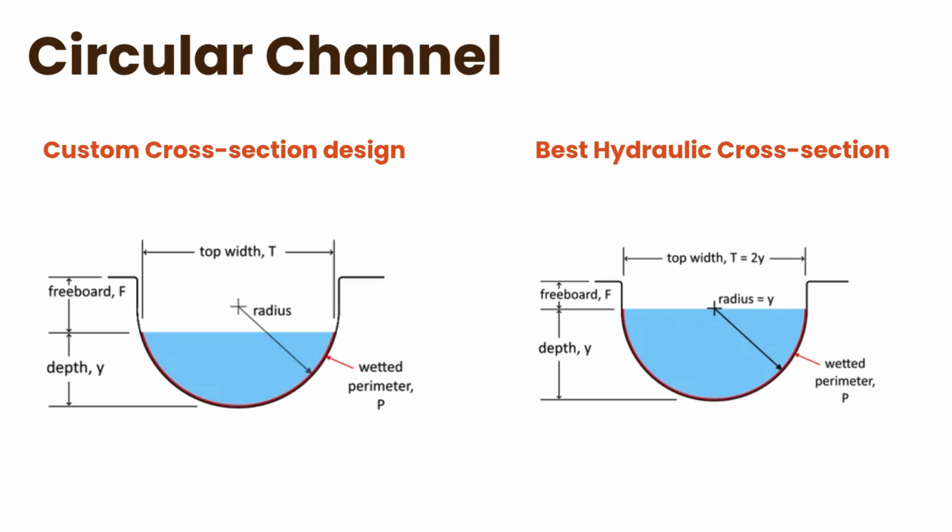They're designed to handle pressure and variable flow levels. Even when they're only partially full, their shape allows water to flow efficiently. Plus, their curved design resists soil pressure very well, which makes them excellent for underground applications.